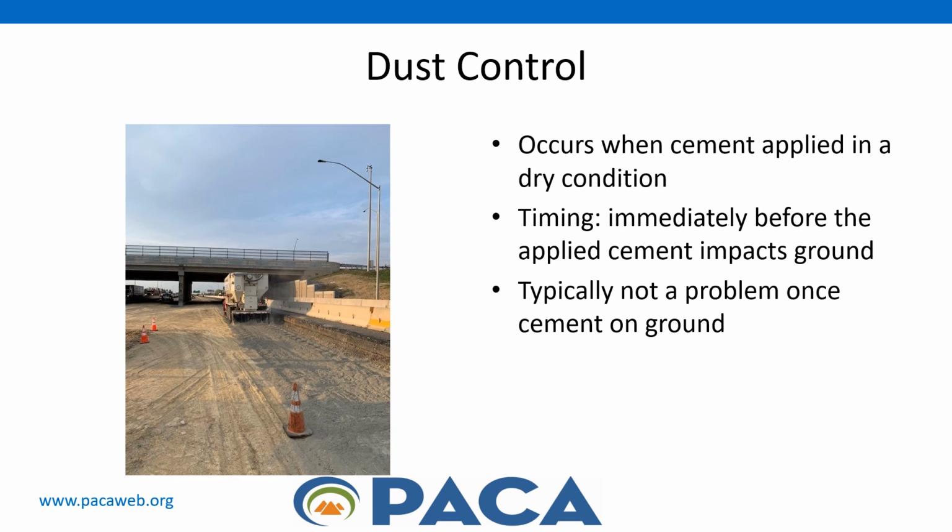Depending on the weather and/or location, dust control may be an issue if the cement is applied in a dry condition. The most important time for dust control is immediately before the applied cement impacts the ground. Dust is typically not a problem once the cement is on the ground, except on a very windy day. Cement spreading equipment typically has adequate controls to minimize fugitive dust during the spreading operation.